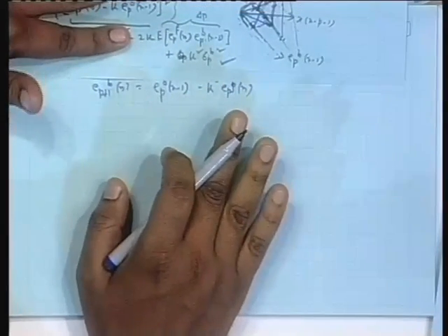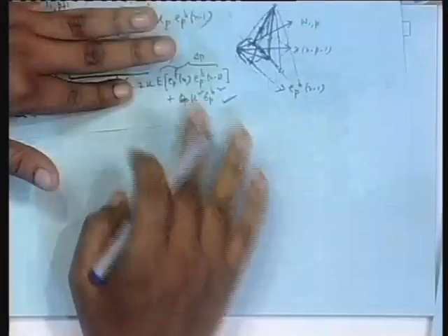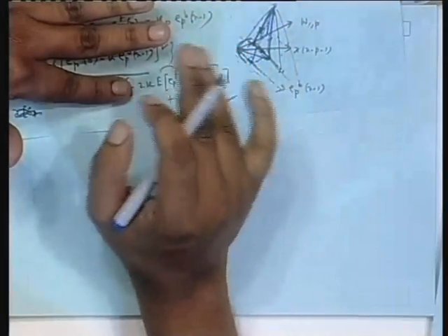They will not remain locked to each other, they will not be the same after convergence also, not only before convergence, because convergence is only in the mean, not exactly on the optimal Kp. So the two approaching and landing on Kp and therefore remaining equal, that situation will not come; they are only oscillating around Kp, the optimal coefficient, isn't it? So there is no guarantee.